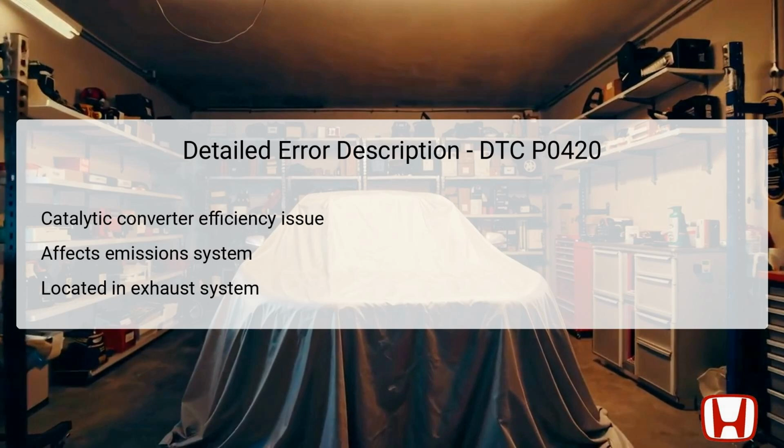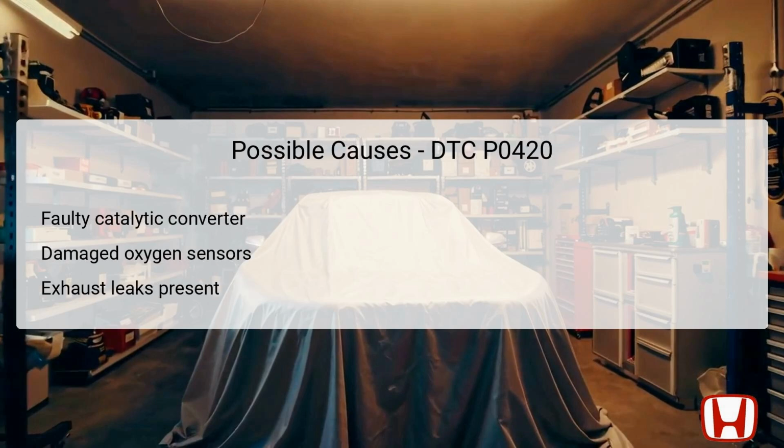If the catalyst is failing, or if there are issues elsewhere in the exhaust system, it may trigger the P0420 code. Accurate diagnostics is essential to pinpoint the actual problem associated with this code and take appropriate corrective action. Several factors lead to the P0420 Diagnostic Trouble Code.